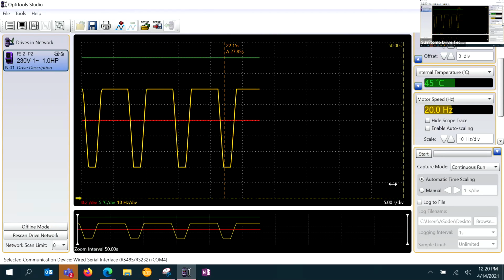So good tool for if you're trying to investigate what's going on with the application, making sure it's not seeing too much amperage, too much speed. If you don't want to overspeed in your application, you can see exactly what it's doing. So definitely a useful tool, and it all can be done via the same wired kit that you've been programming with, monitoring with, and things like that. So it definitely can be a helpful tool, especially for amp draw.